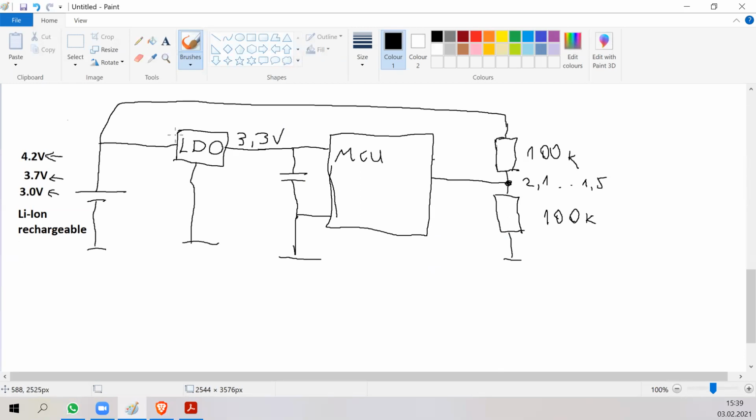Maybe, for example, this LDO also has some quiescent current. And if we add all of these small currents up, the battery might discharge itself through these resistor dividers within something like a year. That is a serious problem, because when you buy batteries, they cannot be shipped full.